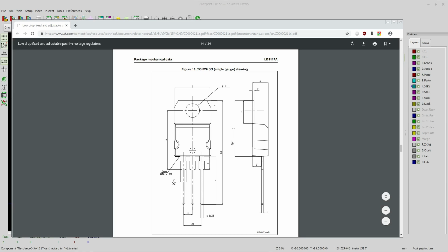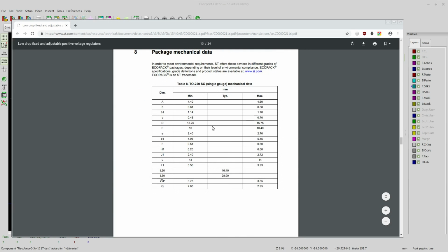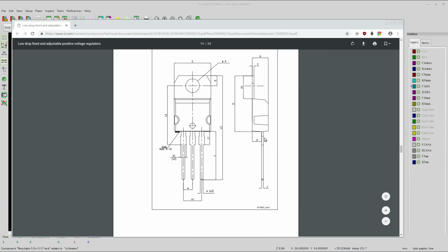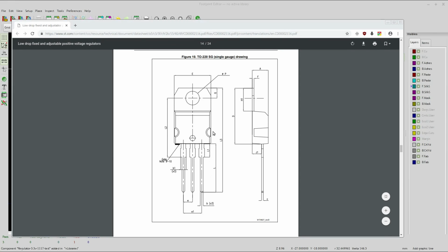Now, so having said that, what's D here? So D, again, is, let's say it's going to be on the far outside. Well, yeah, we could say maybe 16, and then add on another millimeter for that bend right there. So maybe 17, maybe 16 and a half, that will go from the holes to the end of this. So with that value, it does seem like the height of our total box is a little bit longer than it needs to be, but that's okay. But like I said, that was just a guideline, right? Now we're trying to get a little bit more detailed about the thing.